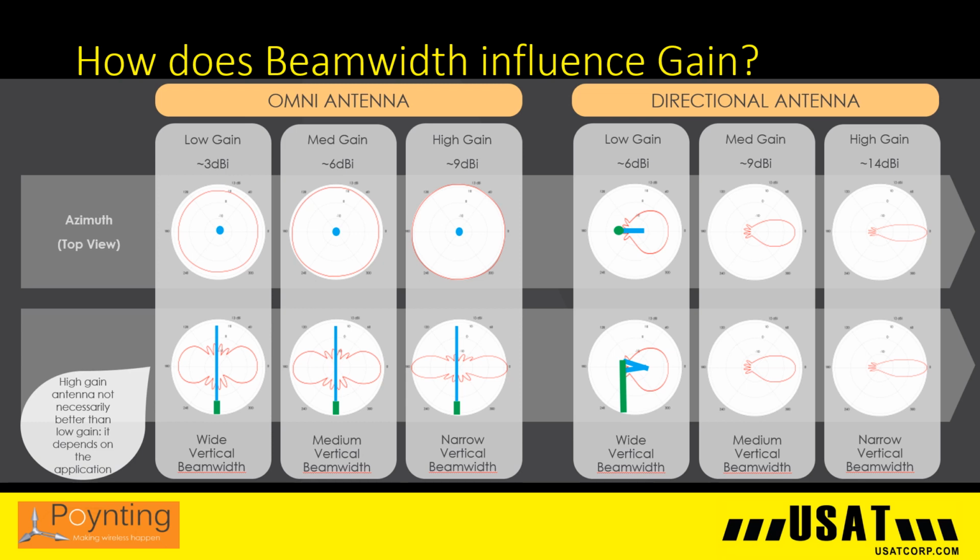Remember I asked the terrain question in the beginning? It's not always about the highest gain. The medium and lower gain antennas have a pattern that is better if the cell towers are located significantly upward or downward in elevation from your site in a hilly area.